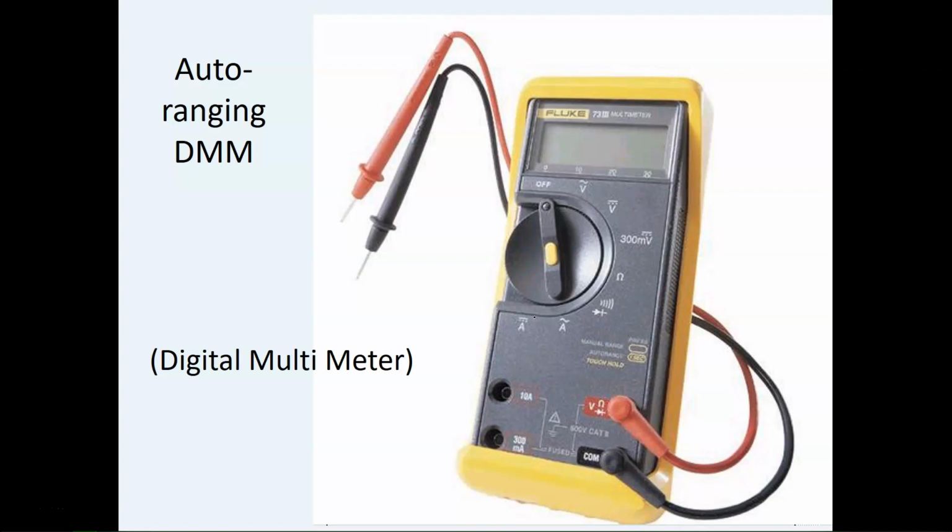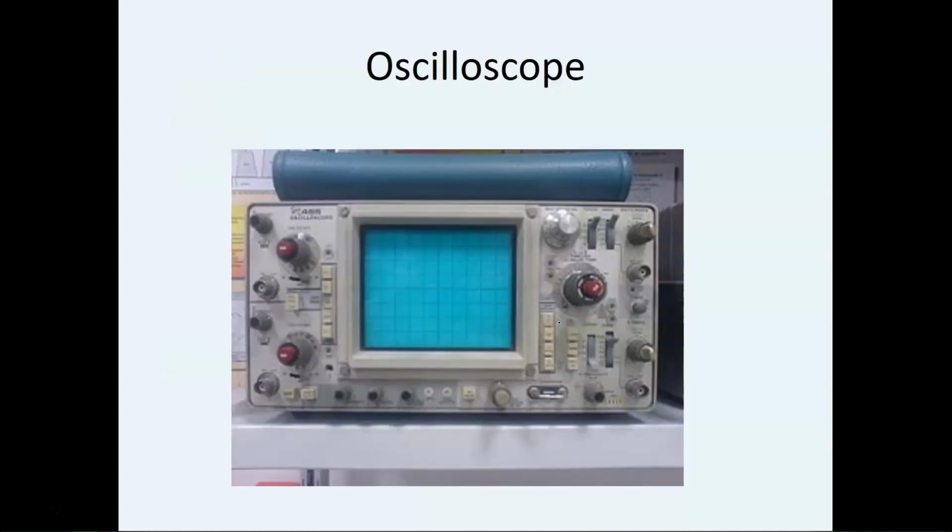But what you should notice is the fact that this does not lend itself to reading milli or microamps. This just basically will read amps DC and amps AC. When you start trying to read something smaller with that, it might not read true, or it might read kind of weird. That's the way I can put that.